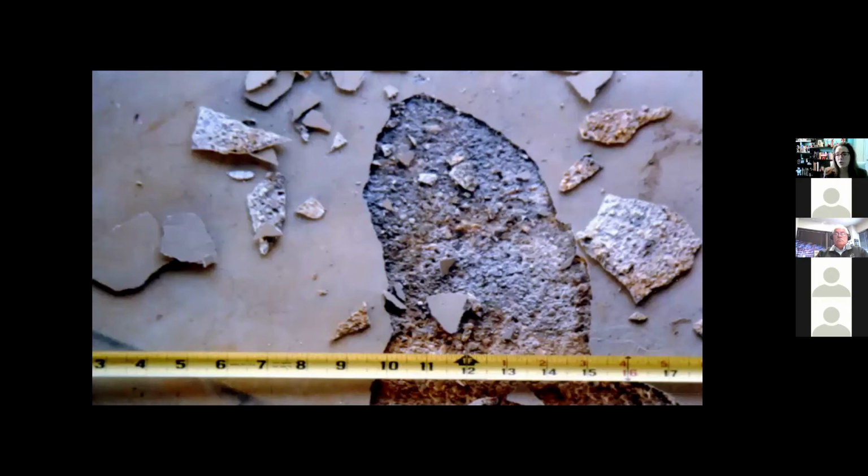Again, it depends. What's that structure being used for? If you remove that top surface, would you have quality concrete underneath? What are your tolerances on finish? Do you need an overlay? So again, it depends, but often delaminations can be from improper finishing techniques as well.